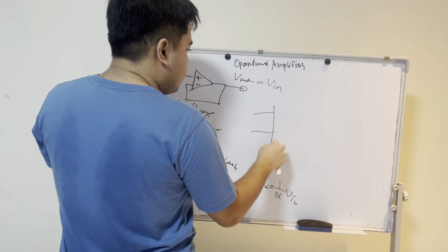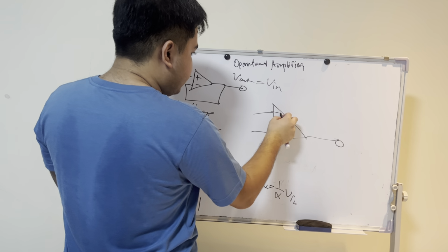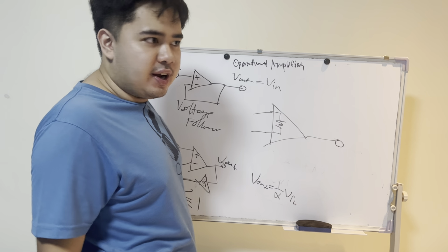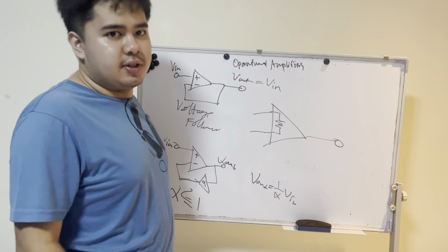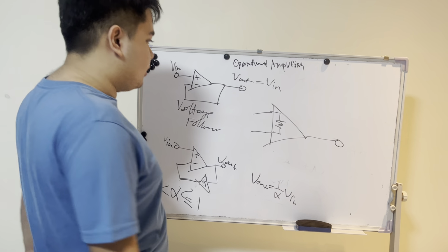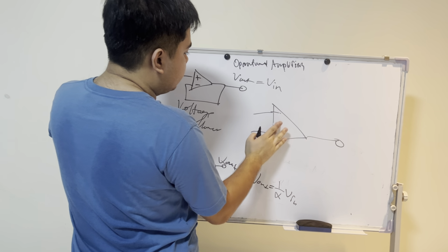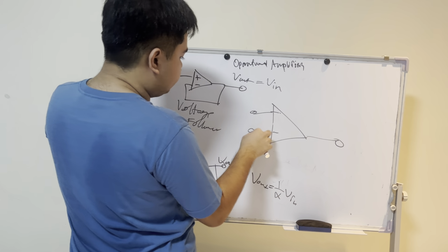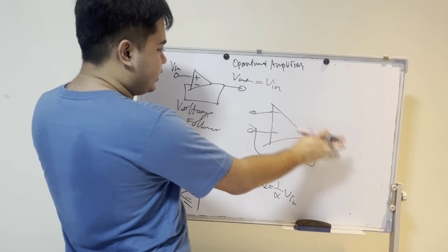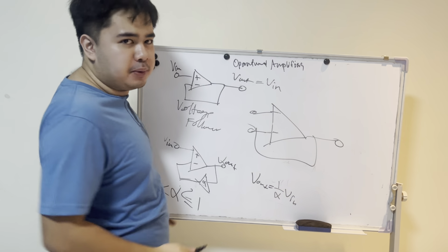So when we have an operational amplifier, right, we expect the inputs to be connected by some resistance or impedance, right? Because the internals of it is just transistors and a bunch of amplifier circuits using transistors. But ideally, this is an open circuit, which means by doing this, the input is disconnected from the output.